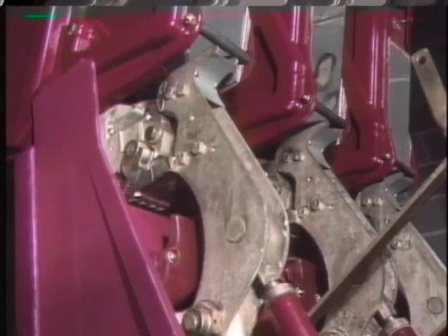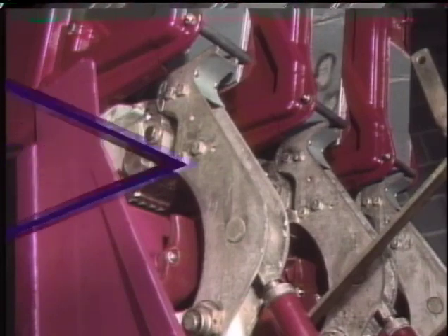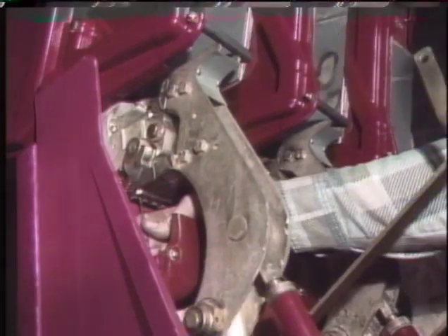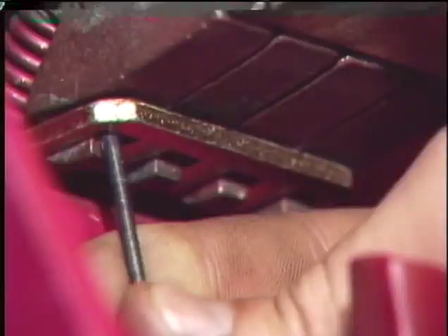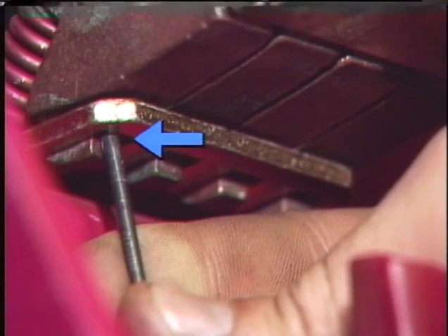A third adjustment check is contact pressure. For this breaker, the contacts are cranked completely closed. A gauge is inserted in a slot that opens under the contacts when they are fully closed. If pressure isn't sufficient to allow space for a specified size gauge, the contacts may need to be adjusted or replaced.